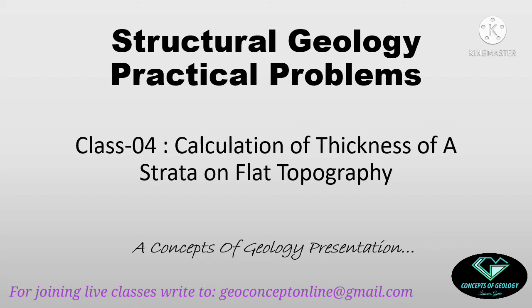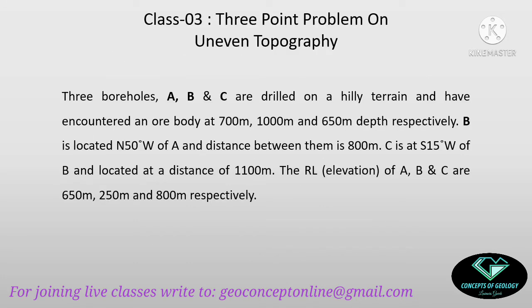But before going to the topic allotted for today, we will solve the problem which was given on the last day. That was the 3-point problem on uneven topography. So let's begin. The problem was, we are having three boreholes A, B and C. They are drilled on a hilly terrain and they have encountered an ore body at 700 meter, 1000 meter and 650 meter depth respectively. How A, B and C are located on the ground is instructed here.